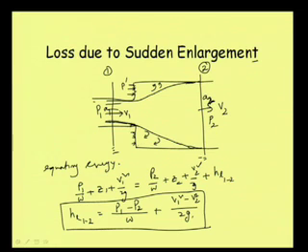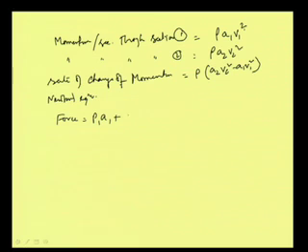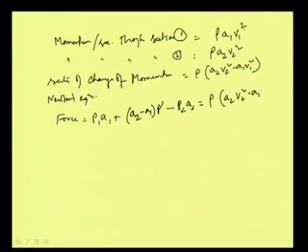From here to here there is no change in section. So, this is the bigger area A2 minus this smaller area will give us the area here, this portion of area, and this area multiplied by P dash. Let us write it like that first, that is (A2 minus A1) into P dash, and minus P2 A2, and this is equal to the force, so rho times (A2 V2 square minus A1 V1 square), fine.